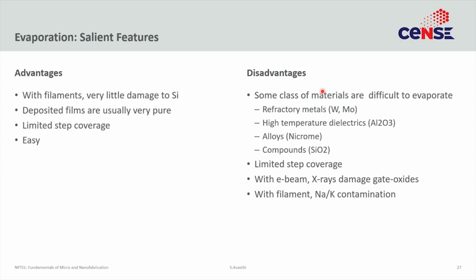The films tend to be very pure, not compared to CVD, but say 99.99% pure. It has limited step coverage, which can be an advantage or a disadvantage. The arrival energy of atoms is very low. It is a very gentle process. Okay. You would think that, oh, you are heating up, you are melting, so the atoms that are raised would cause some damage. No, if you actually measure it, it is very gentle. It is a very gentle deposition. So, it can be done on very soft films.